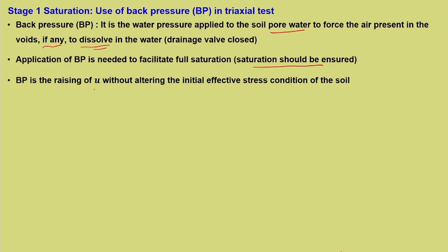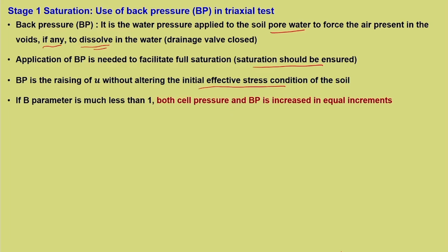So, it is the raising of pore water pressure without altering the initial effective stress condition of the soil. This is very important. The moment it changes the effective stress, then it is going to have its effect on strength. Now, you will probably understand the importance of discussing pore water pressure.